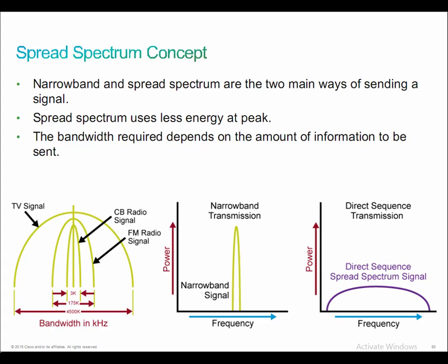But because the signal stays at the frequency for a short time, and in the case of most frequency hopping mechanisms, that time is typically about 300 to 400 milliseconds, and then it jumps to another frequency, that interference doesn't really affect our transmission for a large amount of data. And because we're typically using TCP-based applications, and we have protection mechanisms in our communication control, we can mitigate the damages of the actual data that's being transmitted.